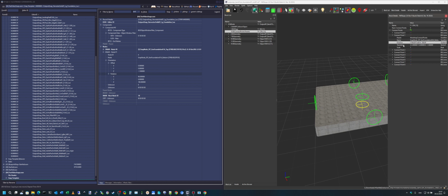Rotation is first and translation is second. So sometimes I start writing here like 90 or minus 180, but this is wrong. You want to put offset with the translation, and it's 2, 0, and minus 1.5. Sorry, 0.5.